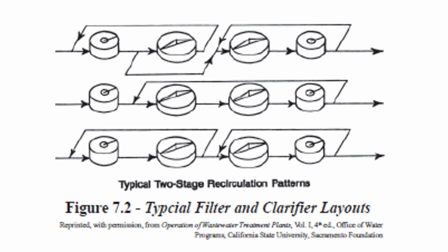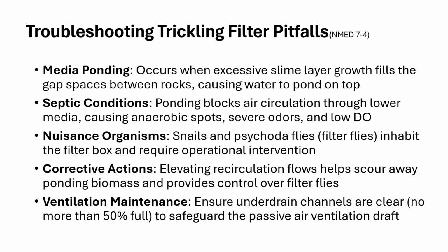So like I said, these are pretty versatile systems. They're not the end all be all, but they do have their use. Okay. Level 3 and level 4 examinees, you should understand how to troubleshoot trickling filters. So you should understand what some of the problems you have are to begin with.